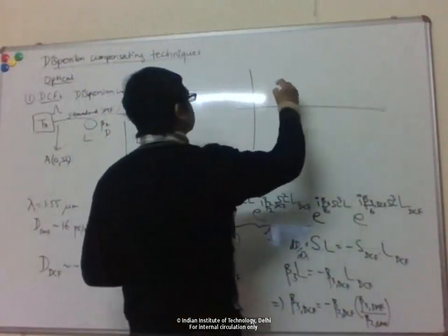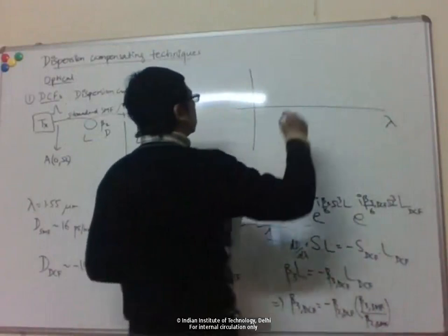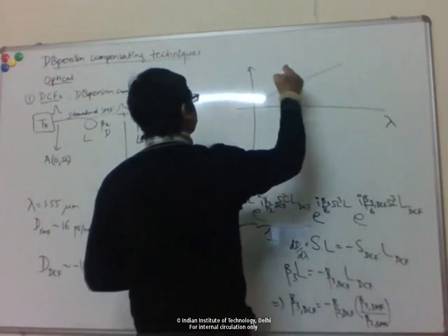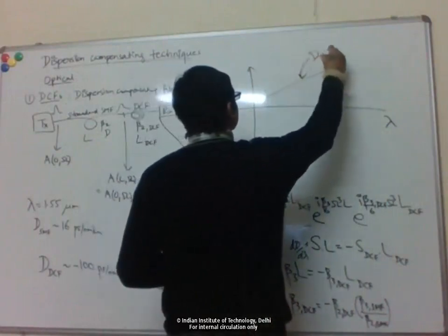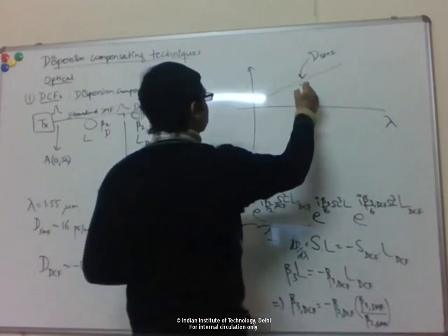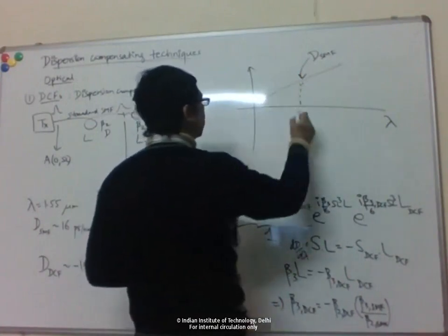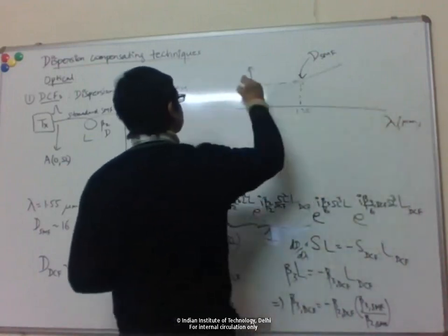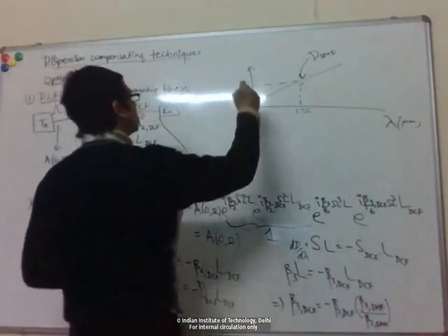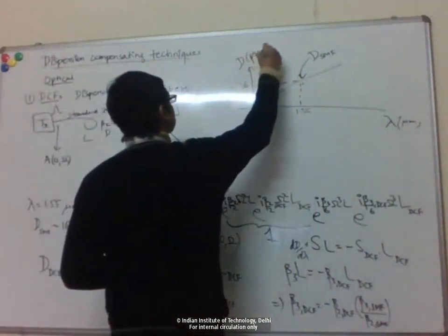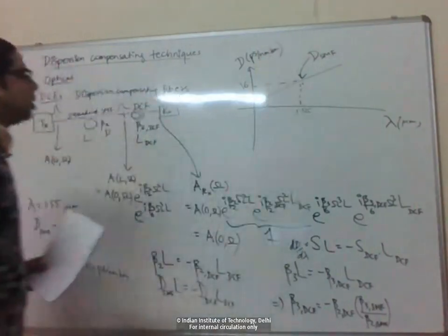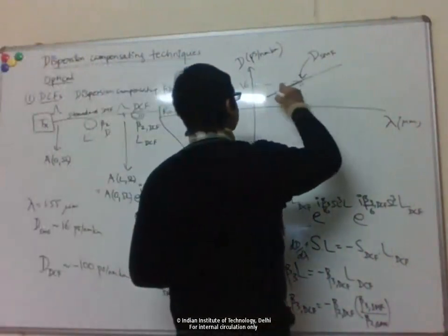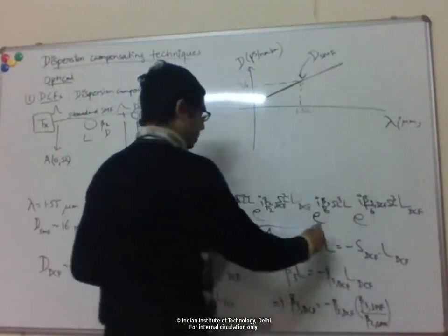right. So if you plot dispersion versus wavelength, right? So typically, let's say it has something like this, right? We saw for the standard single mode fiber, it will cross 0 around 1.3, and at 1.55 micron, this is about like 16 or something, right? So there is a slope, right? The dispersion is wavelength dependent, and there's a dispersion slope, which is this S, right?